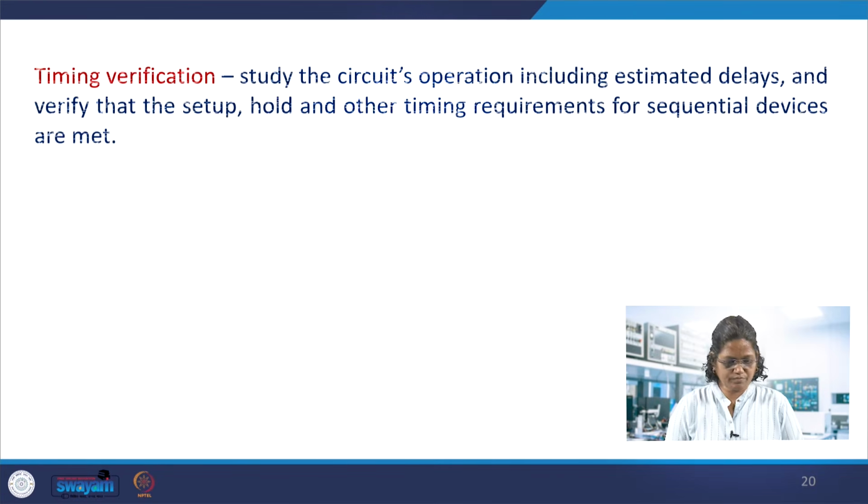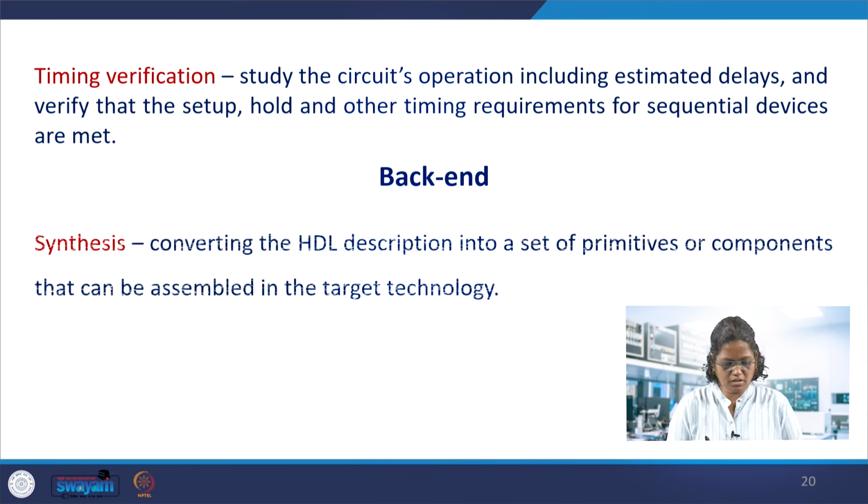In the case of timing verification, the estimated delays are considered, such as the setup time and hold time required for flip-flops, especially in the case of sequential circuits. Sequential devices need the setup time and hold time, and estimated delays are also considered in the timing verification. The backend converts this description into components, the primitive hardware resources for the technology targeted.